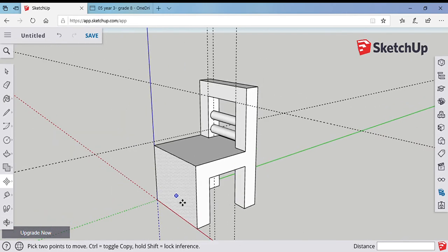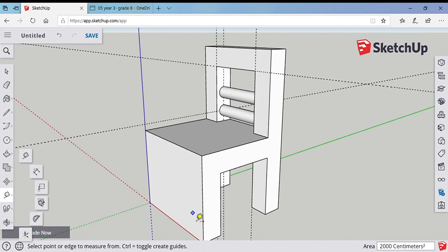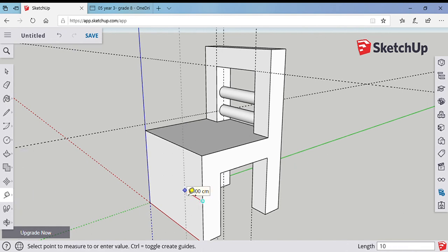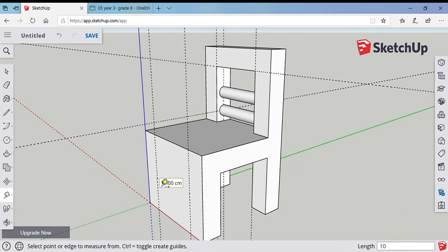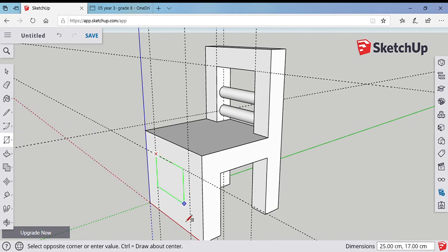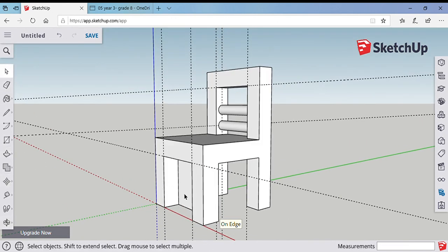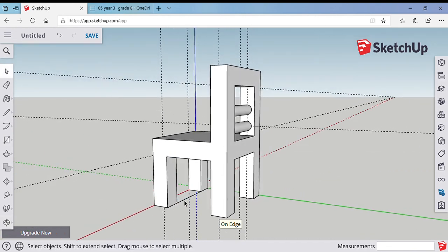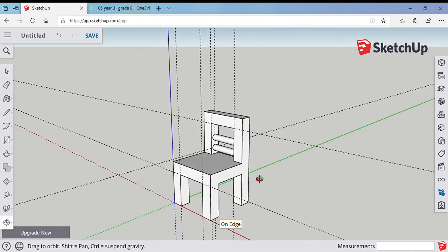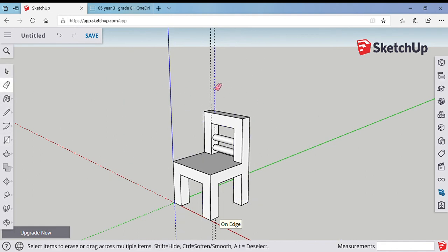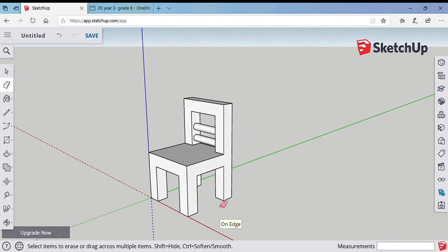using the subtractive method. For the front, you can use the same method, 10, 10, and 10. You draw a shape and then push-pull to the back. That's what I was saying. You can always select the surface that's from the back and press delete. This is it. And you can always get rid of the extra construction lines so that they will not confuse you. Good luck!